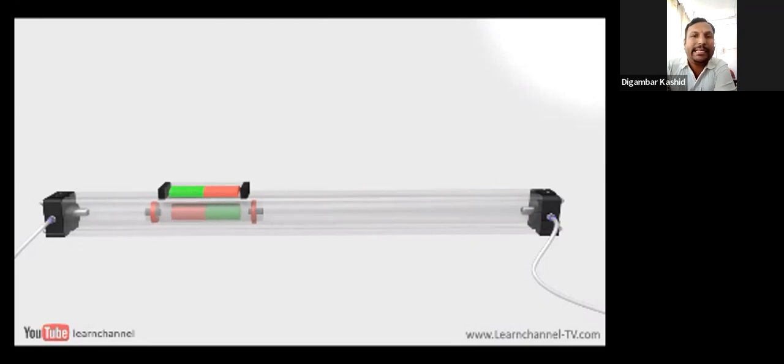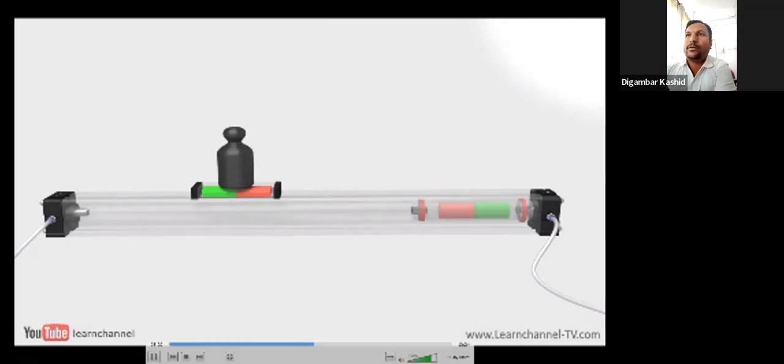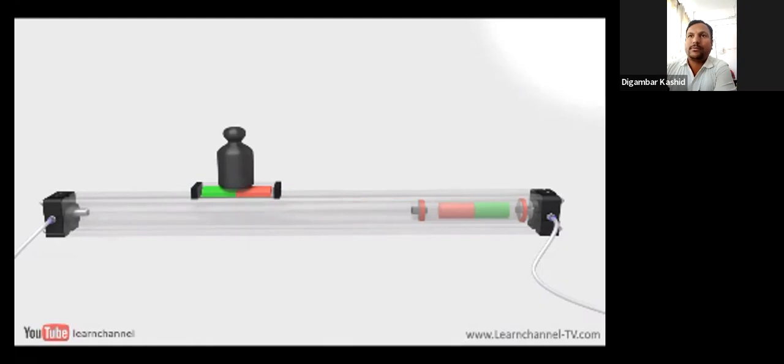In this design, the piston can move in a completely enclosed thin steel pipe. You get a leak-free cylinder with less wear compared to the other types of rodless cylinders and no ingress of contaminants. However, the magnetic coupling is also a force limiter. If the load is too high, you have to worry about decoupling.